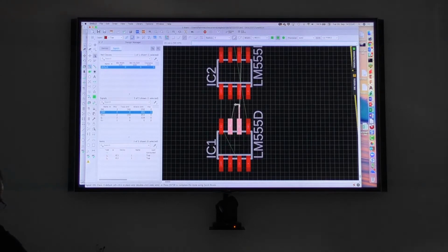Now I go straight up here. You see, now I have optimal conditions for connecting. So that's something you have to think about. If you have a different number of components with different pitch or with different grid settings, take the smallest one, adjust this one because that's the most critical with the smallest pads, and then you can always jump into a wider, bigger grid too. But that's something you have to do in the beginning.